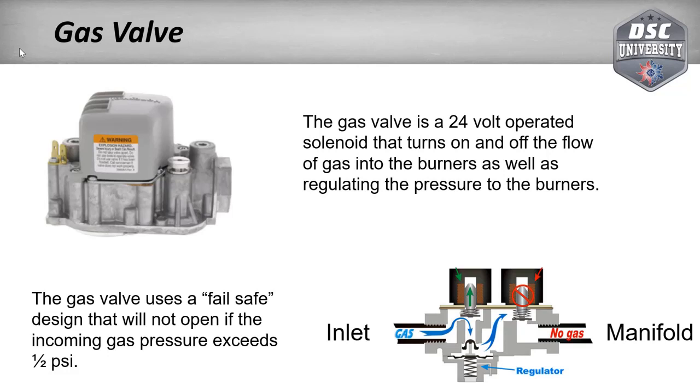I got this little picture down here on the bottom just to show you how a gas valve works inside. And the thing about gas valves is they're what's called a fail-safe device, which means if it fails, it's going to fail to the closed position. It's not going to fail to the open position where it could just sit there and let gas come out uncontrollably.